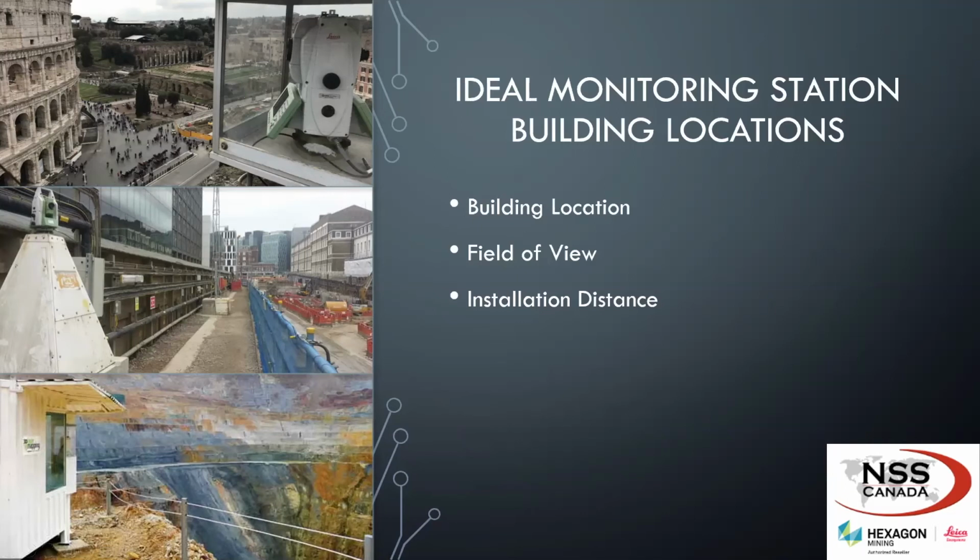If, for instance, you have to install your total station on something that is moving, what free station does, before it actually monitors, is orient itself first by shooting different prisms. It says, hey, I changed from this position yesterday to this new position, are you okay with that? Yes. Boom. It's going to monitor and show you the displacements.